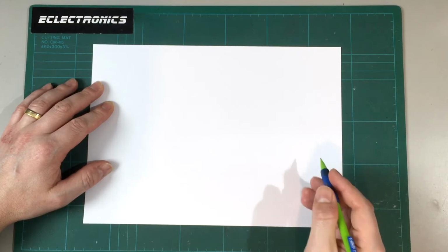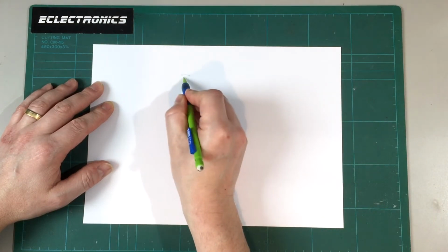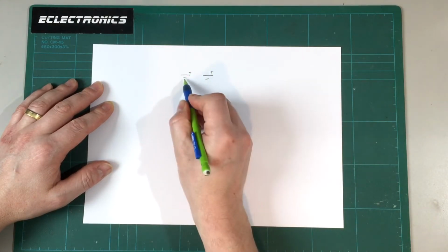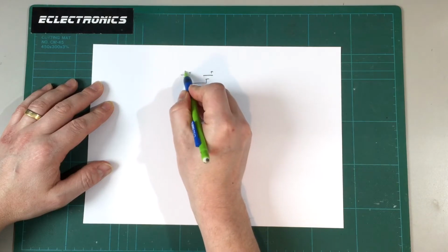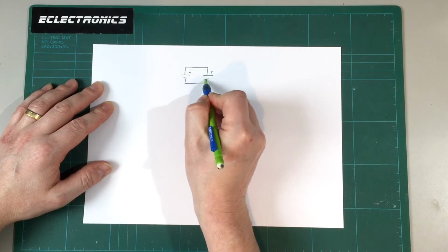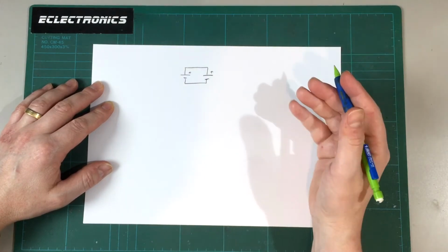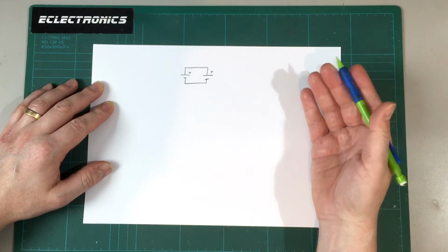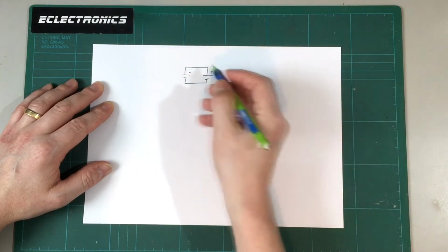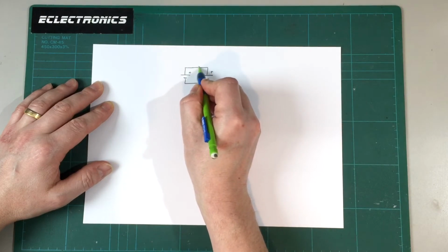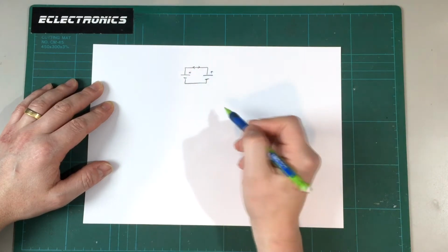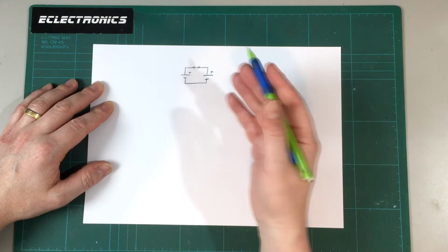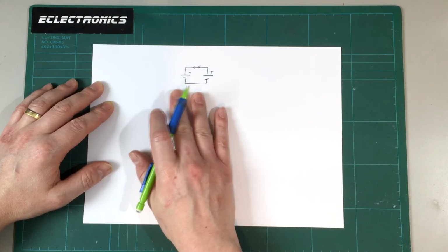So let's go back to the fundamentals and say, right, we have two cells. What would be the easiest way to balance them? Well, if they were independent, then we could simply connect them in parallel. That would force the voltage on each cell to be the same, and because we're doing voltage balancing here, that means effectively we're going to automatically balance the cells. They're connected in parallel. Some current's going to flow, don't know which direction it's going to flow in, depends on which cell has the higher charge initially, and that current's going to keep flowing and it's going to decay away until the charge is equally balanced between the cells.